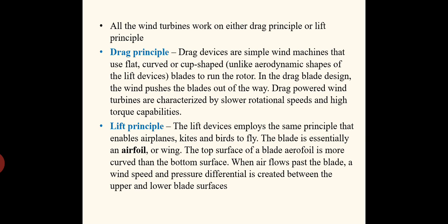Drag devices are simple wind machines that use flat, curved or cup-shaped blades to run the rotor. See, the blades of the wind turbine working on the drag principle are either flat-shaped, curved or cup-shaped. Okay, so there is no aerofoil shape. That is important, unlike the aerodynamic shapes of the lift devices. So this is what I have told. The wind turbine models placed in front of our college and in front of the lab are based on the drag principle only.